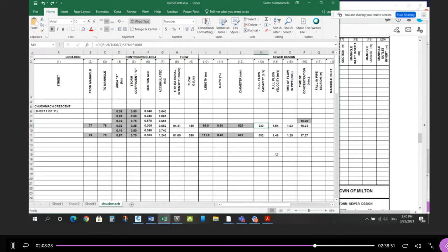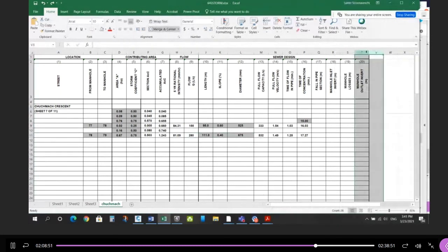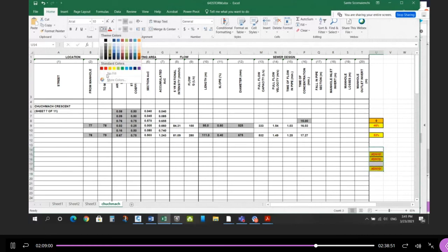So then what you do is you can compare, right? This capacity has to be greater than this, and it is. And this capacity has to be greater than this, and there it is. So it works. So these pipes are big enough with the size and the slope combination. The size and slope combination yields a capacity greater than the expected flow. And again, if you want to, what I typically do is I unhide this. I typically calculate the capacity. Okay, I don't need these, sorry. Let me just get rid of these.